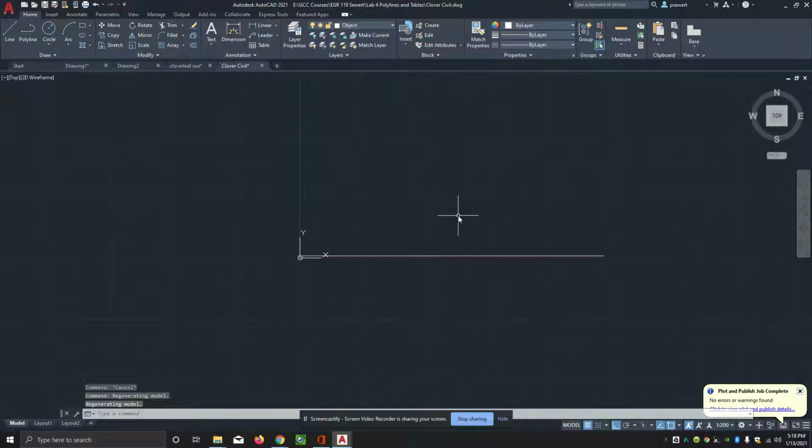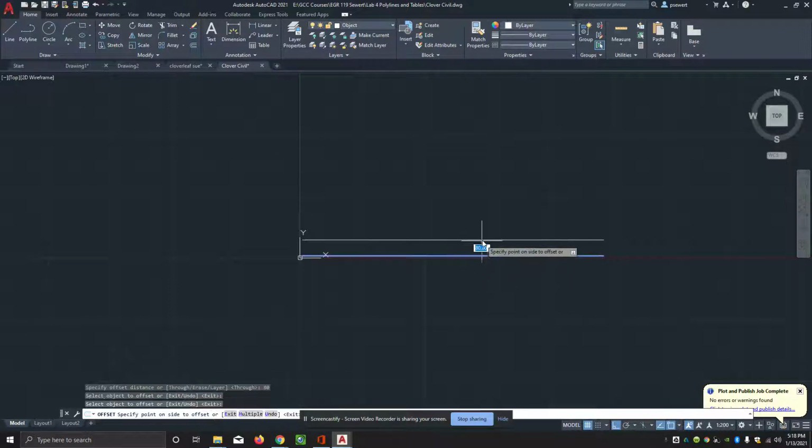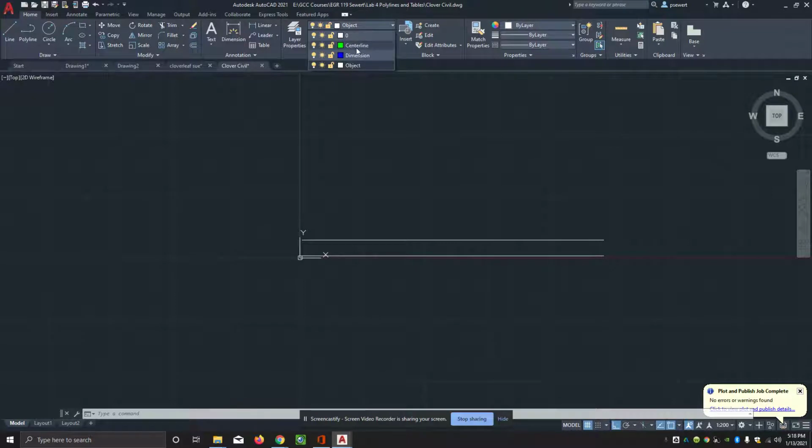Zoom out a little bit, and then at this time, all I would do is do an offset command. And we know that first offset is going to be 60. So then you just go 60. Okay, hang on, just to get an idea here. So it's 100 foot between. So let's go. I'm going to change the center line and do an offset this time of 30.